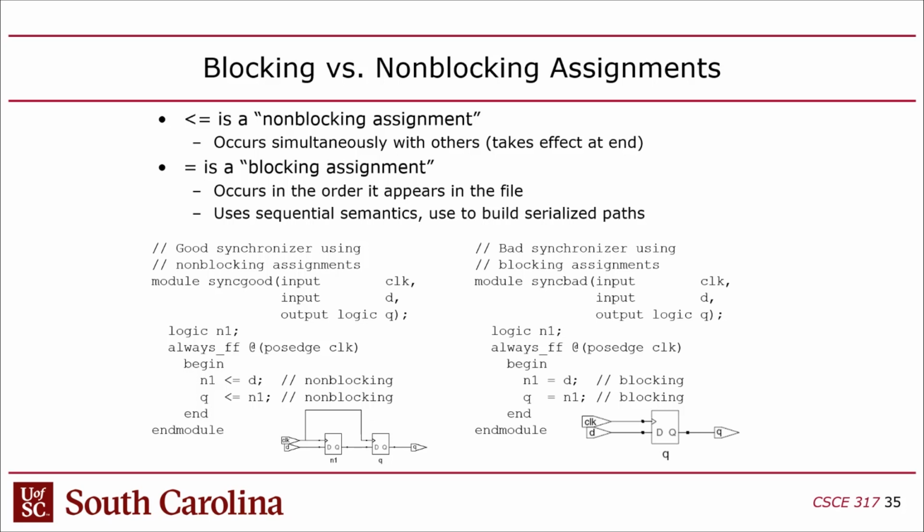Now, why is that important? It's not for this class. All you have to know is if you write sequential logic, clock logic, you should use less than equal, and if you do combinational logic, you should just use equal. You guys with me?